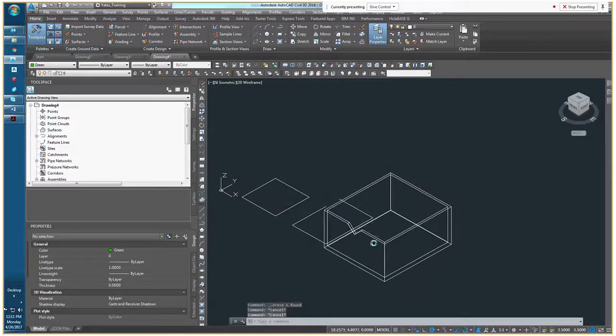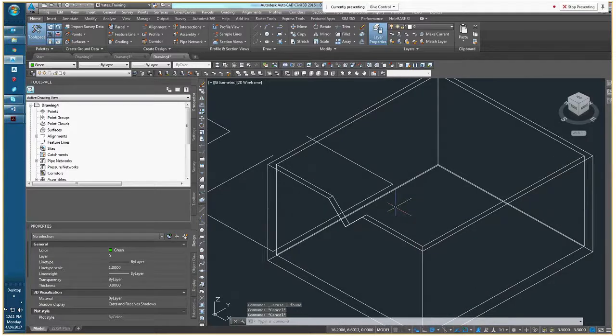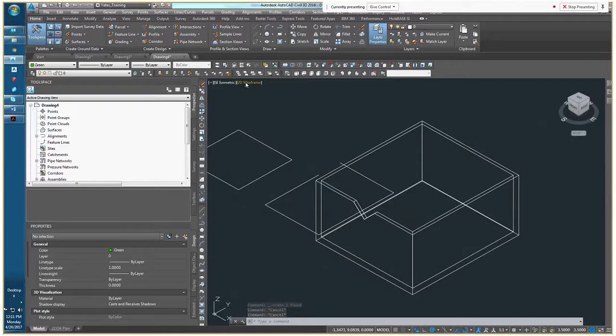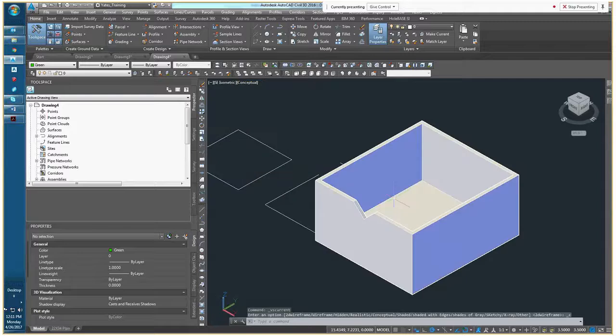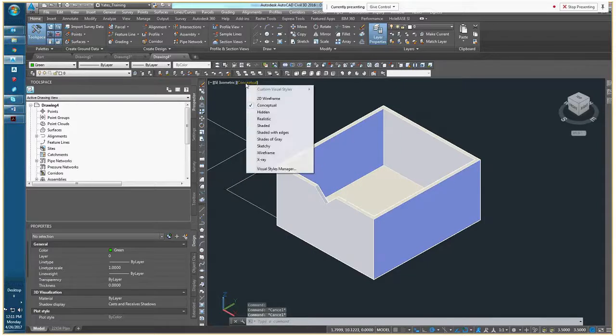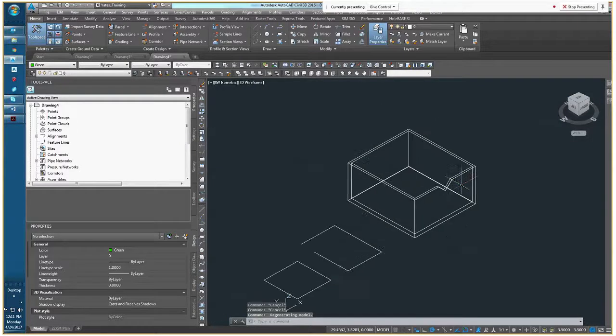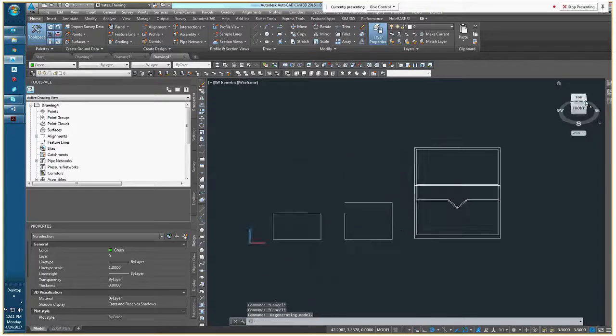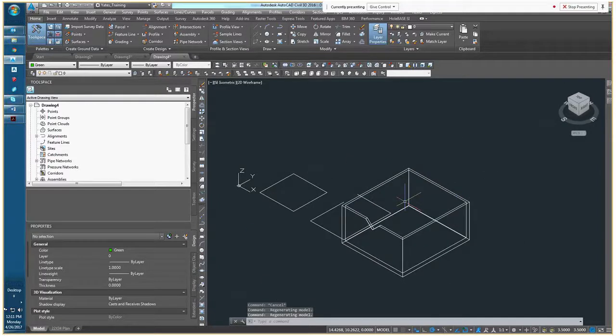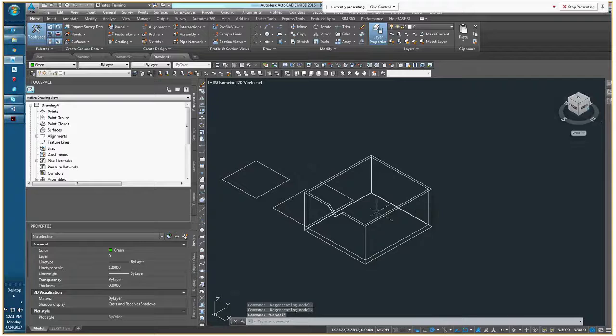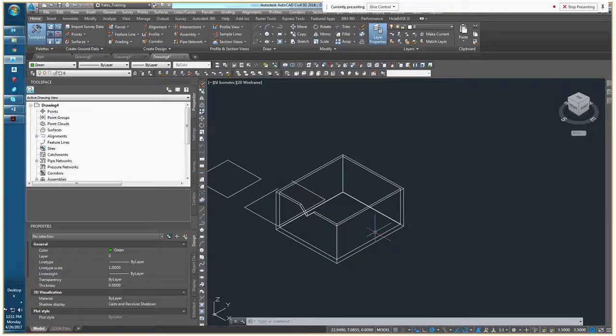Okay? Now, if I was to insert a detail of this onto my drawing, what I would likely do is actually use another command called the flat shot command. All right, so typically how I use flat shot is I'll go from an isometric angle that I want to display on my drawings and start off my view cube with an isometric angle just by clicking on any one of these corners. So I've got a sort of southeast isometric view set up, and I'm going to type in the command flat shot.